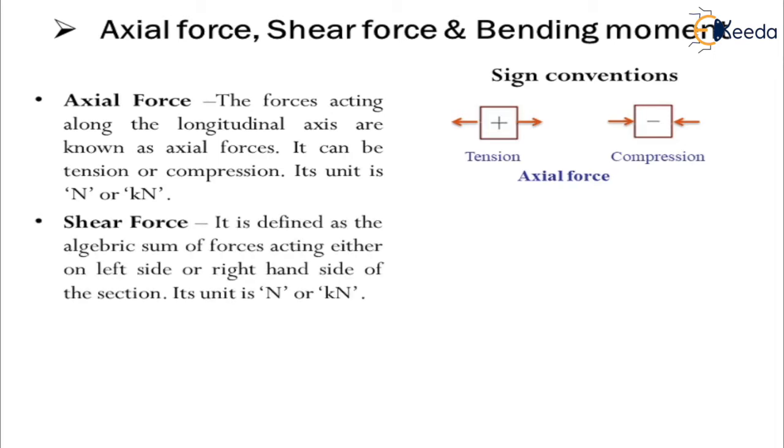Now, second force, shear force. Shear force is defined as the algebraic sum of forces acting either on left hand side or right hand side of this section. Its unit is Newton or kilonewton.